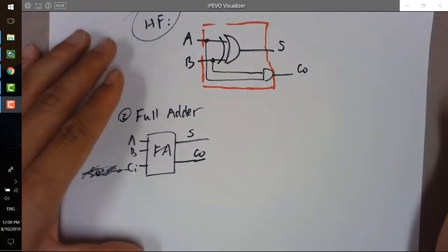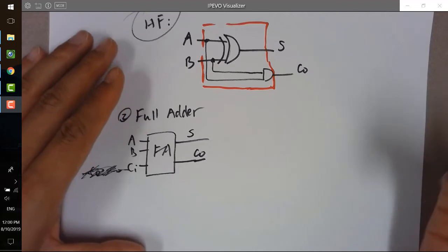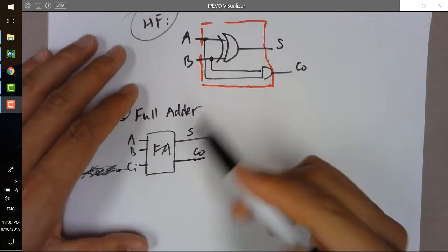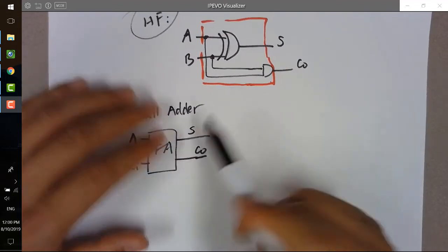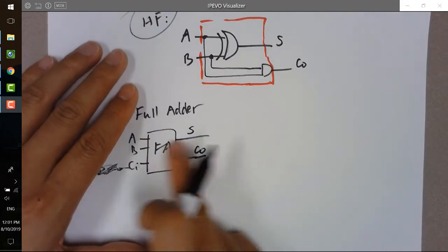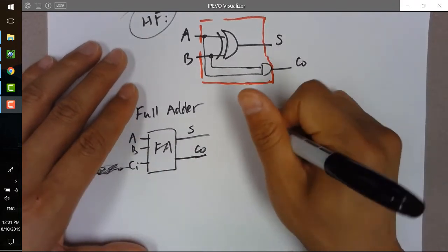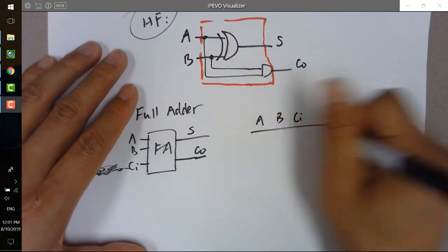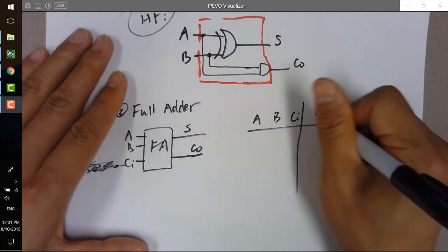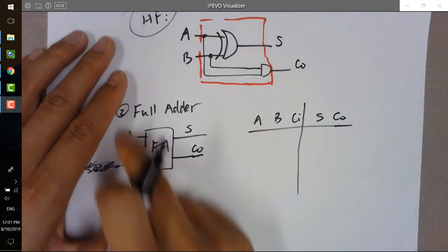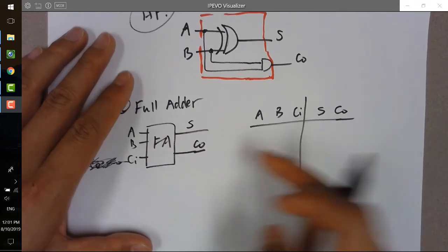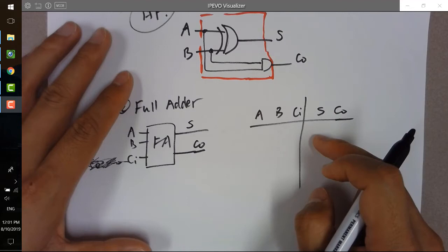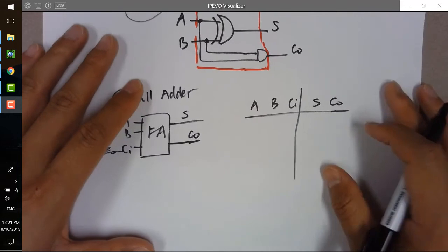That's it. So when a customer asks a computer engineer to build some digital circuit for them, they will let them know the first thing: how many inputs do I have, how many outputs do I have, and then what's the logic or relationship between the input and output, which is a truth table. So keep in mind, what are these steps when you start doing a digital design? It's actually starting from the function block. You know how many inputs, how many outputs, and what are the relationships among all these inputs and outputs, so you can get a truth table, and then you can simplify that and design the logic block out of that logic, and then get a circuit out of it.